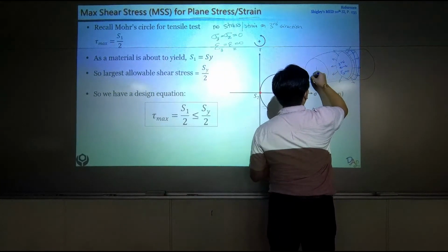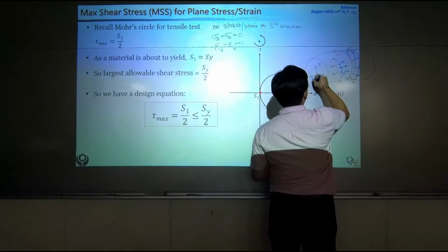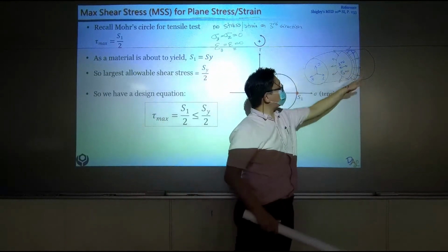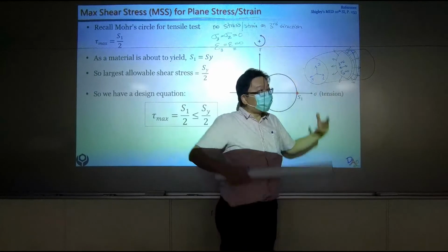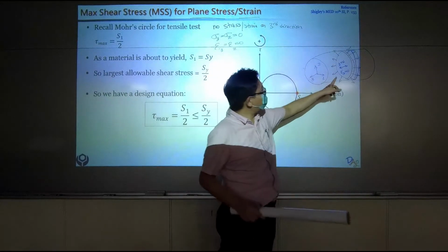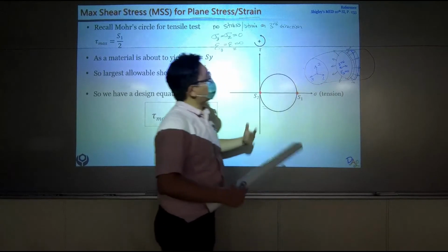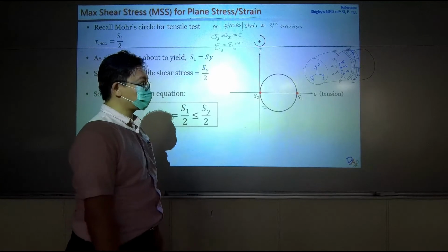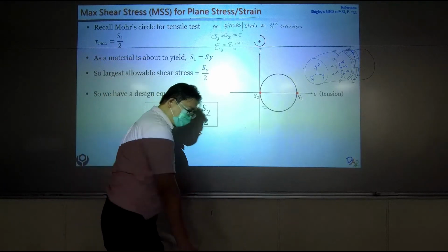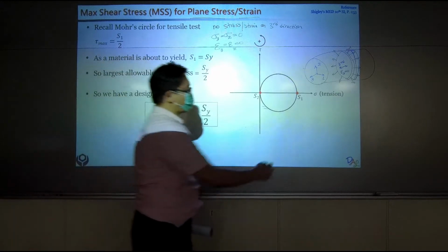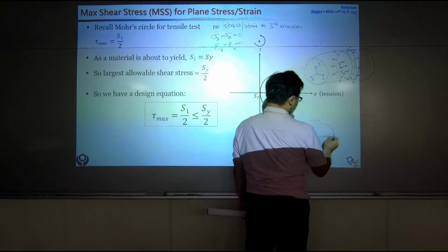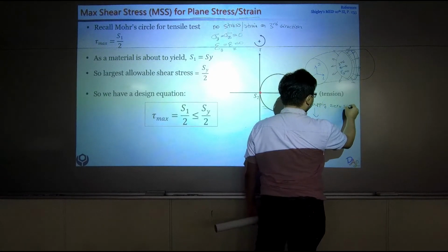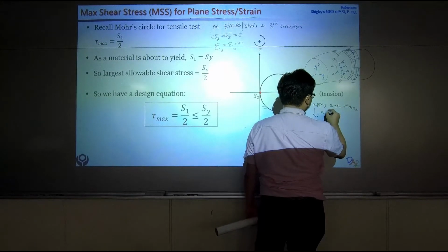If the coordinate system is like this, 1, 2, and 3, there cannot be any movement along the third direction or the z direction. So in this assumption, there's no movement. The strain can only be zero. Okay, that's called a plane strain problem. So how about plane stress? For plane stress, it's basically a plate. Basically a plate, and you apply zero stress along the third direction.